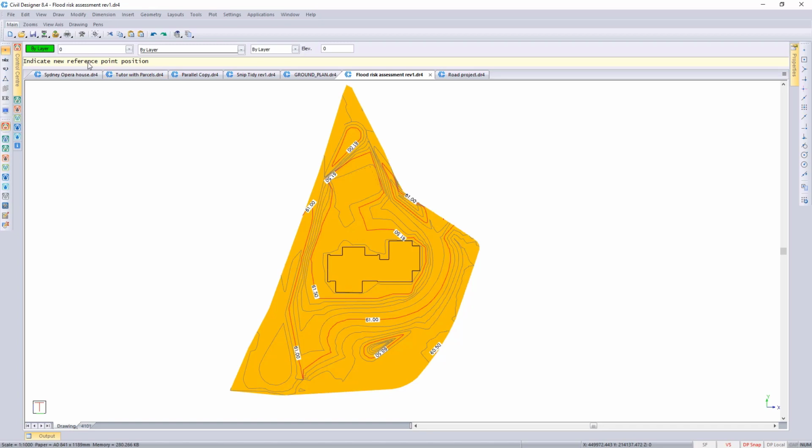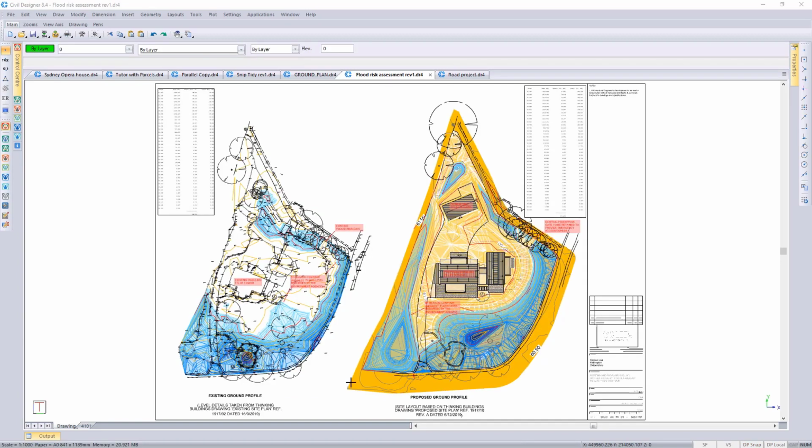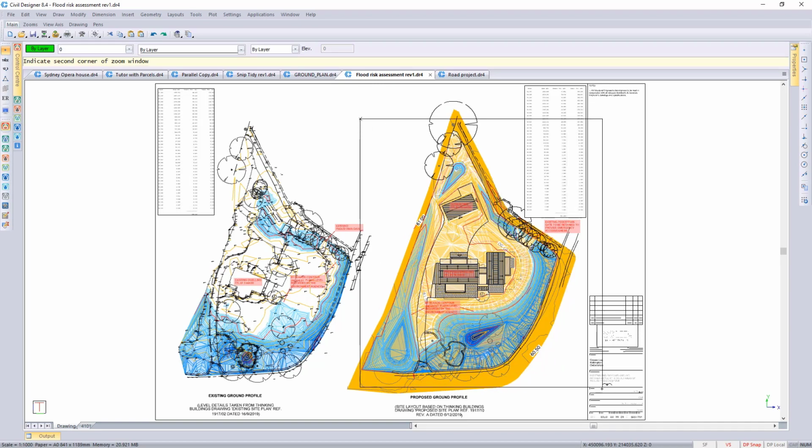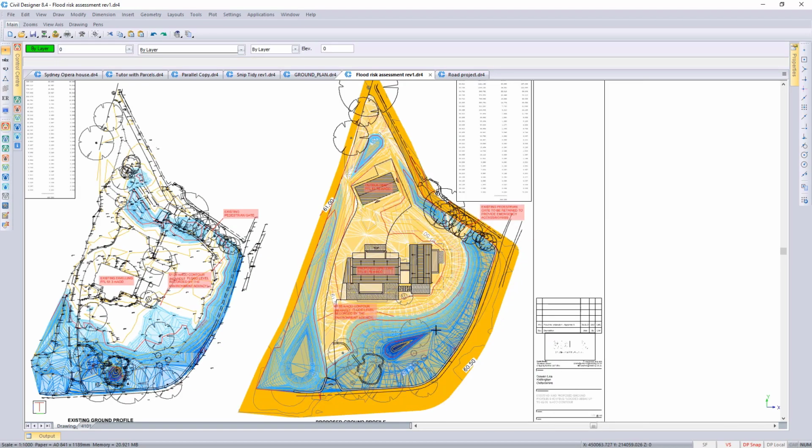You can see the prompt at the top. So I'm just going to click on this side of the drawing. You could use the scaling and rotation factor, or you could always modify and scale and move your PDF into the perfect position. But generally the PDFs would just be used as a reference, background referencing tool, and not strictly speaking for the actual design.